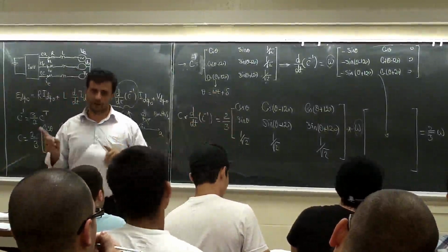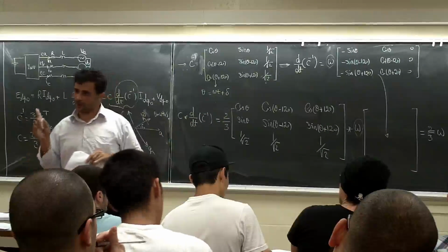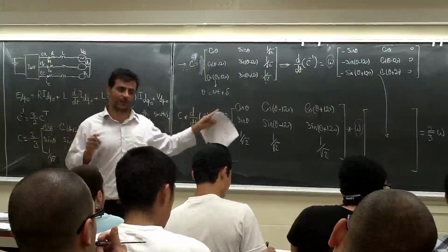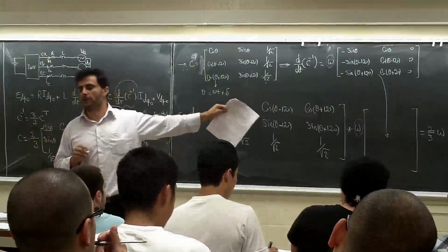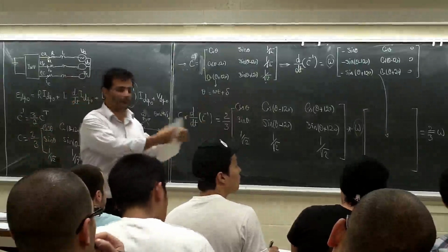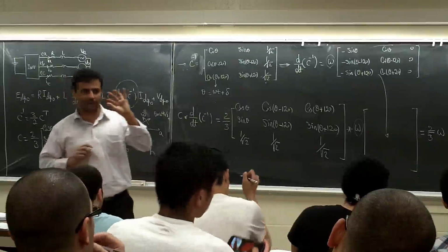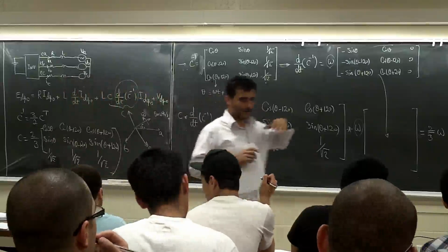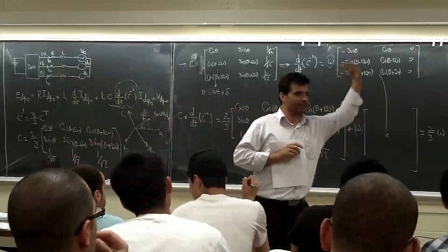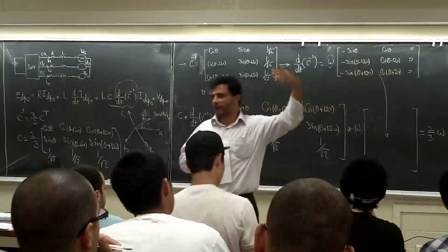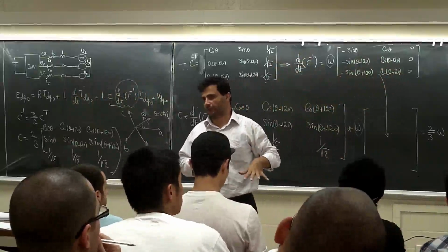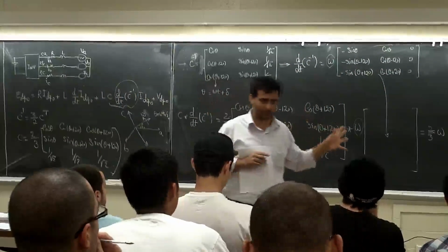When you do the ID IQ control, you can see when you change the ID value, it's going to start to change a little bit. Even when we decouple it, it's not going to be perfectly decoupled. This is the math we are putting there, but in reality it's a little bit different. But we try to minimize that effect. When you change your P value, it doesn't affect your Q value, and when you change your Q value, it doesn't affect your P value. Active and reactive power, I'm talking.